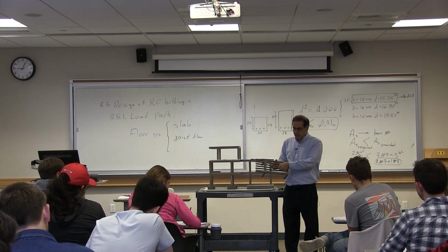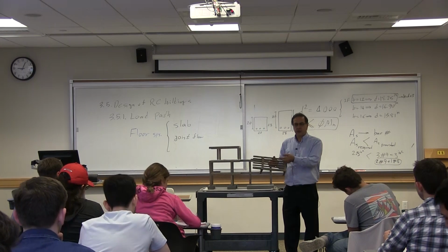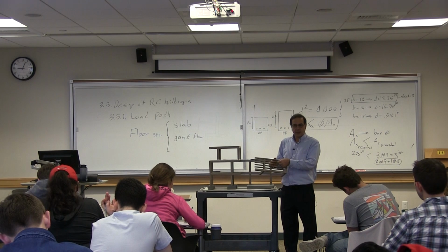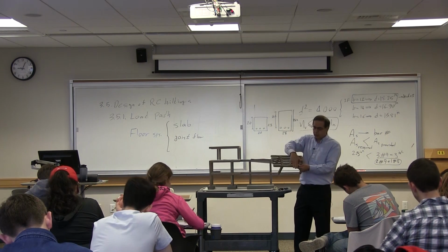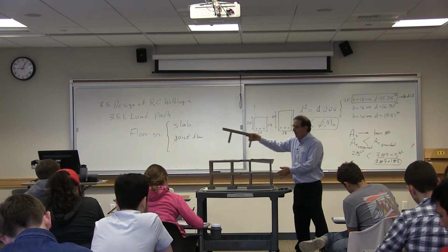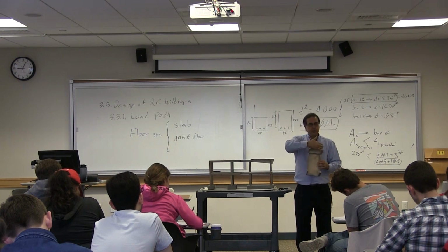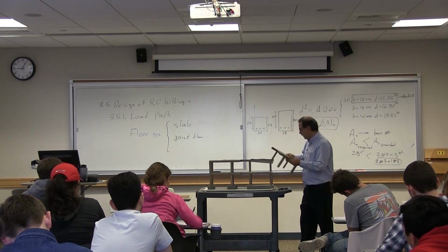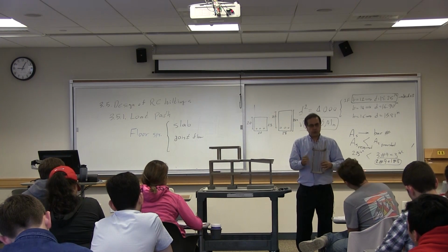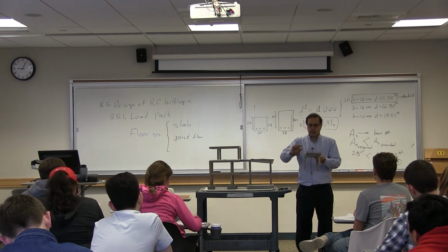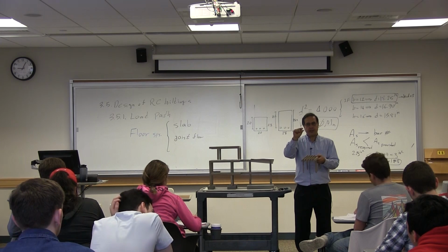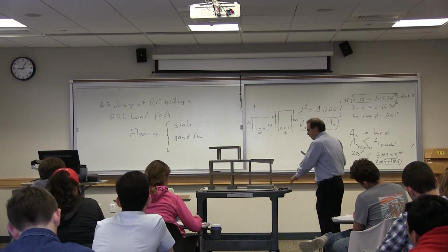These are joists. Joist is practically a small beam. So we have these joists, and then because we have the joist, the slab does not need to span from beam to beam. The slab can transfer from joist to joist, which is shorter. Therefore, the slab that would cover everywhere becomes thinner. That is one type of design.